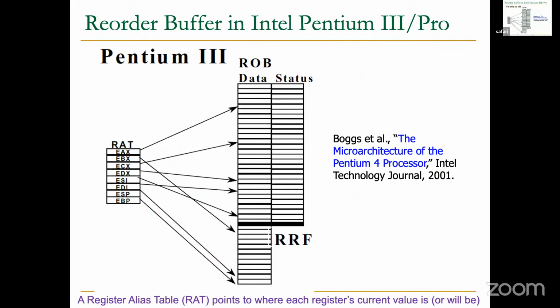Okay, I need to do something else, which is this. Okay, it's the same slide. So this is real. So as you can see, this is actually Intel Pentium Pro, which is the first really commercially successful out-of-order execution processor. And you can see that this is the register file. It's called, actually, this is the mapping table. This is the tags that I showed you. And these are the 8 registers. And basically, if an instruction is sourcing a register 0, this is an index that tells you register 0 is in the register file, architecture register file, or it's coming from reorder buffer entry X. So they basically separated the tags from the register file over here. But it's essentially the same concept.